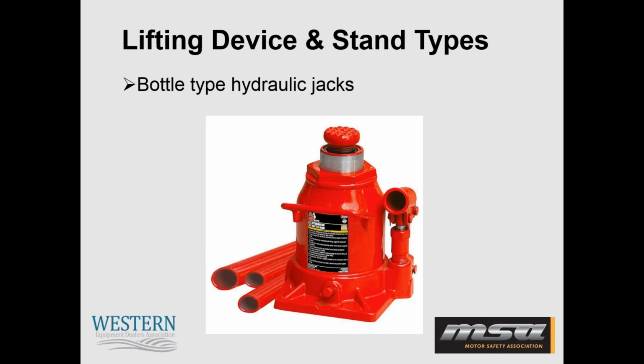Then we have our bottle type of hydraulic jacks. These are very compact, as opposed to the floor jacks, and they're often rated for heavier loads than what floor jacks are. And because bottle jacks usually have a smaller footprint on them than floor jacks, they may not be as stable as what a floor jack would be. Be sure to use your bottle jack on a strong flat surface, such as a shop floor, to minimize the chance of movement. These jacks are basically utilized by putting the handle into the plunger and pumping it upwards and downwards to raise the hydraulic bottle jack.